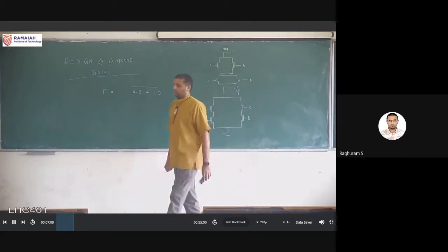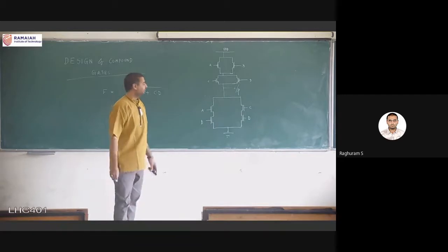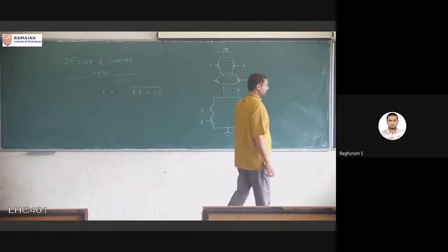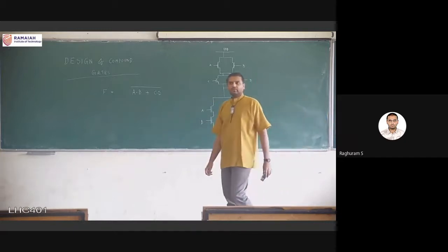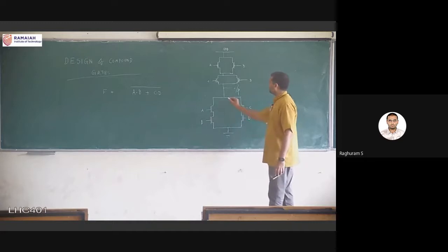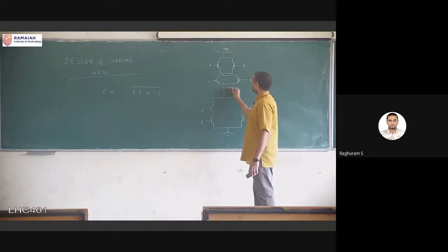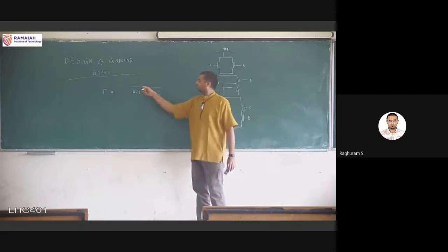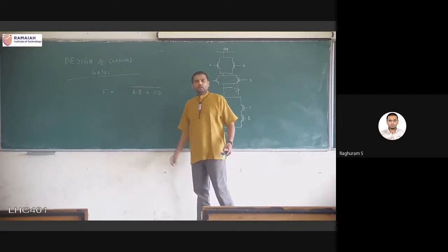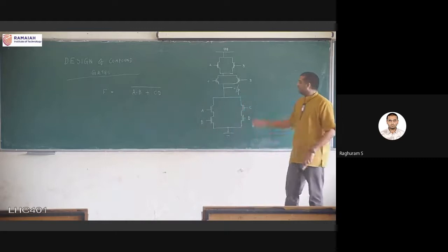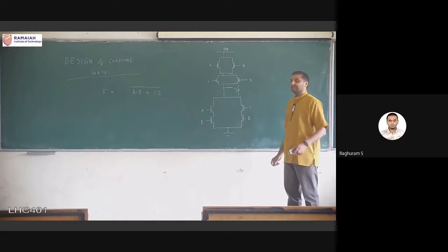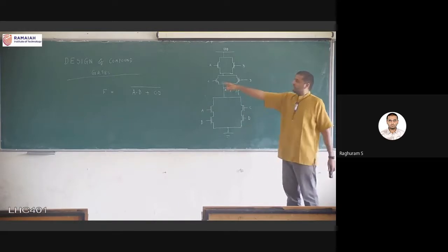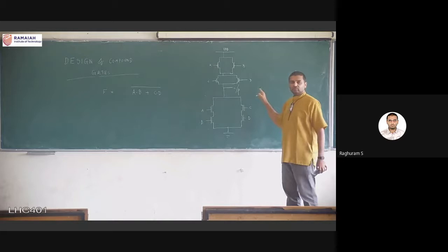Okay, and on top power supply VDD. So this basically is a circuit for our function. And one more thing, we mentioned this also, but all these are naturally inverting. So even though there is a bar here, okay, automatically the bar will come. We don't have to add an inverter at the output node. So this basically is another thing to remember. Okay, just because the bar is there, don't add an inverter here. The bar comes with the nature of the circuit.